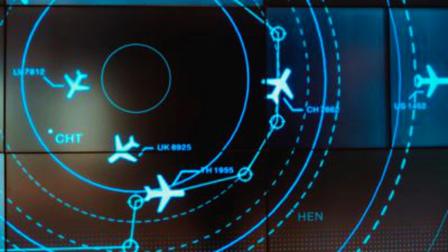Also, ATC may release you to resume own navigation after vectoring you off course momentarily for a variety of reasons, including weather or traffic. Upon initial contact, state your aircraft or flight number, the altitude you are climbing through, and the altitude to which you are climbing. The controller will verify that your reported altitude matches that emitted by your transponder. If your altitude does not match, or if you do not have Mode C capabilities, you will be continually required to report your position and altitude for ATC.